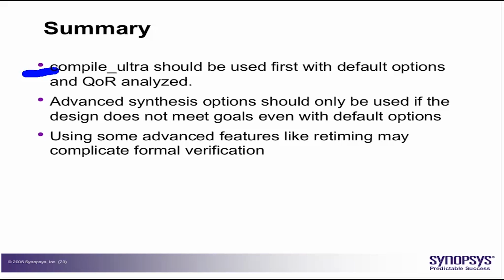Like we saw in lab 4, some paths in the same group which are of low priority, like IO paths, input and output paths, can cause a register to register path to violate. So make sure that your groups are correctly created, and for very critical paths, create a separate group so that we can focus more on that. So first, use group paths.